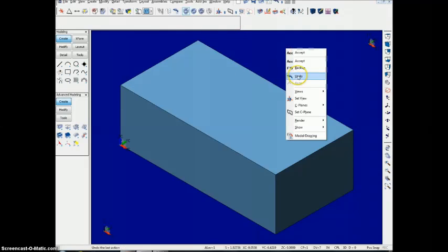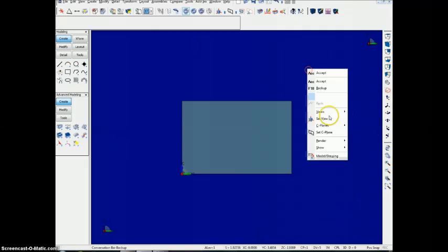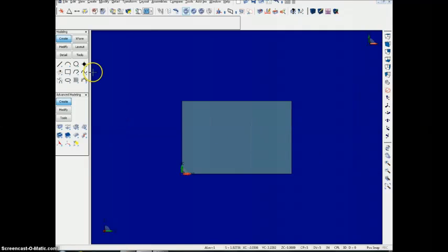Now to begin, I'm going to start by using the trim solid curves tool on the right side of the drawing, so make sure you set your views and C-planes to the correct side. I'm going to use the line parallel distance, and it is 0.75, from the left and right side, and 0.25 from the bottom.